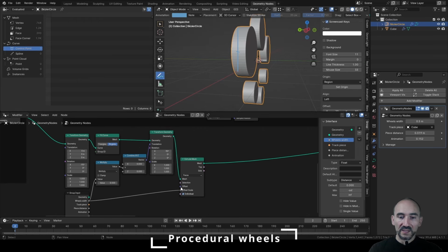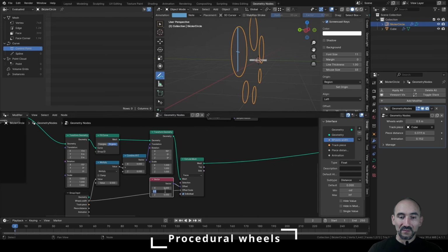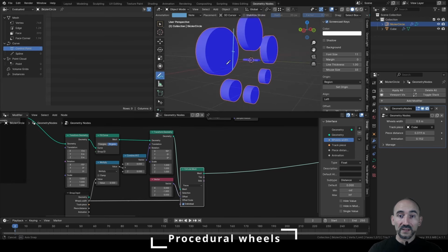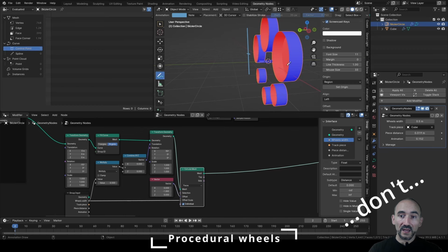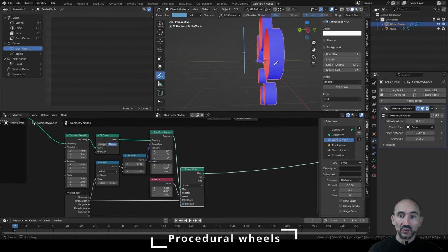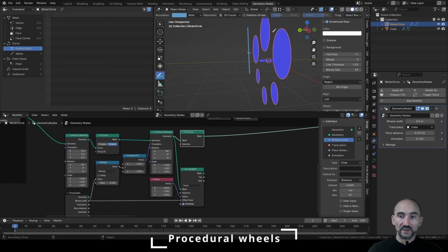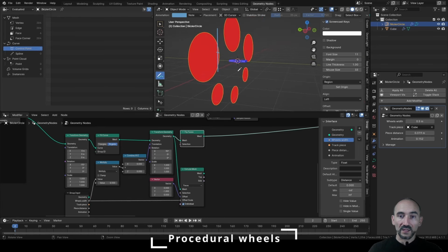To be more precise, I can link these to a vector of the offset and set -1 for the direction of the axis we want to extrude. Then if I enable the face orientation, you can see the correct extrusion, but we can't have the cap here. To close this surface, I need to take the original fillet curve and flip faces. There are these faces here, remember? Okay, the normal of the blue and the red.